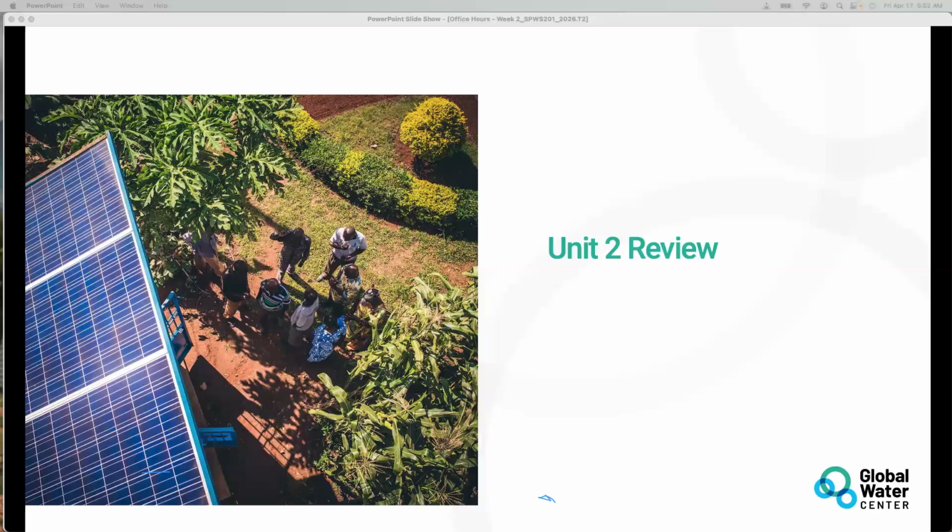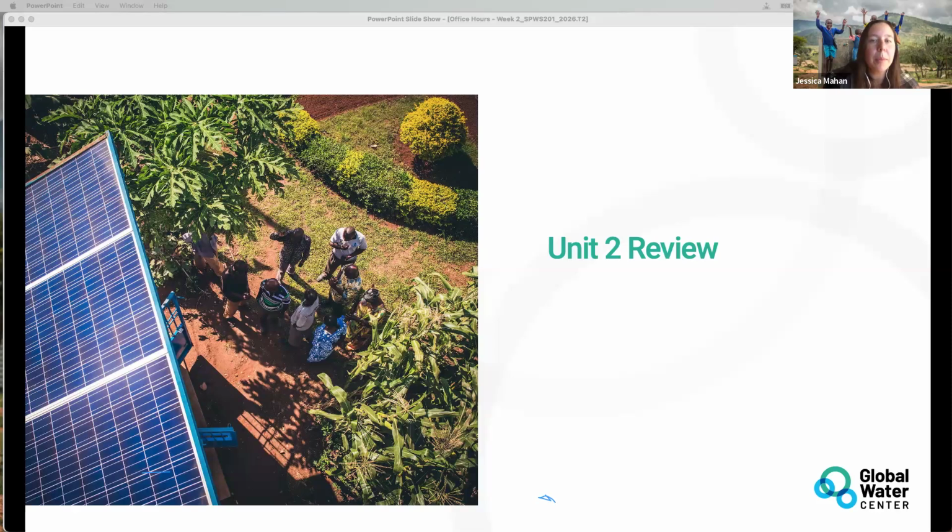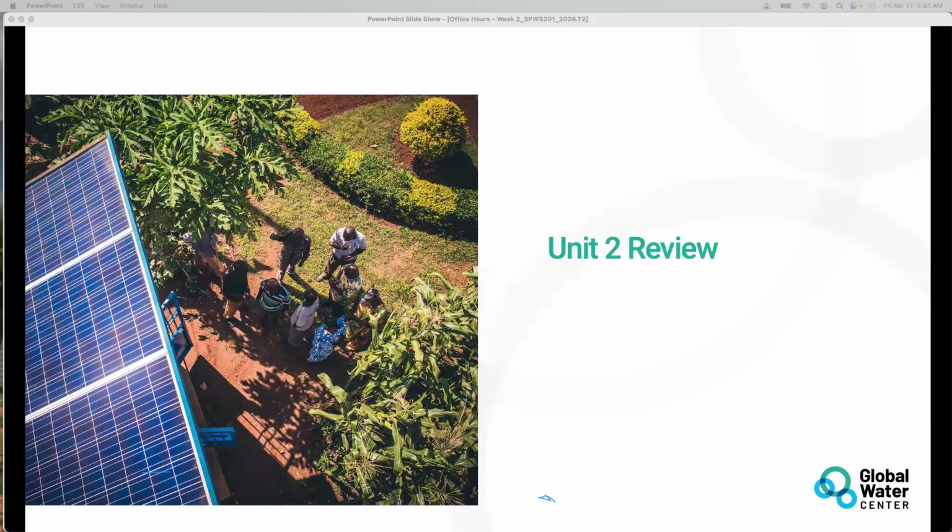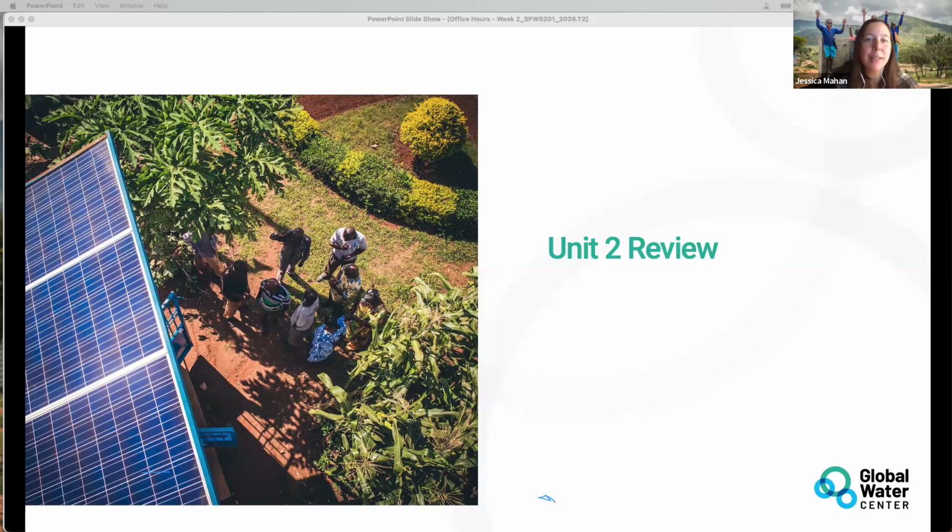Okay, let me clarify. Are you asking for recommendations on when we would do 24, 48, or 72 hours? Yes. Okay. So in my experience, when we can, it's best to do a longer pump test.